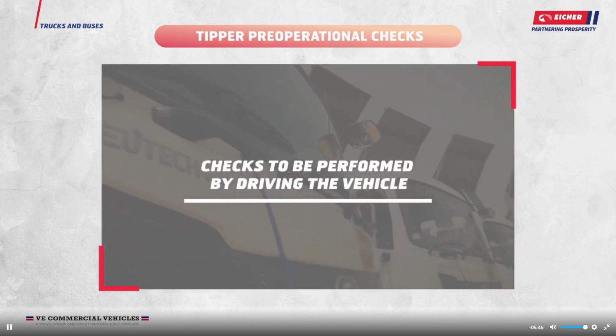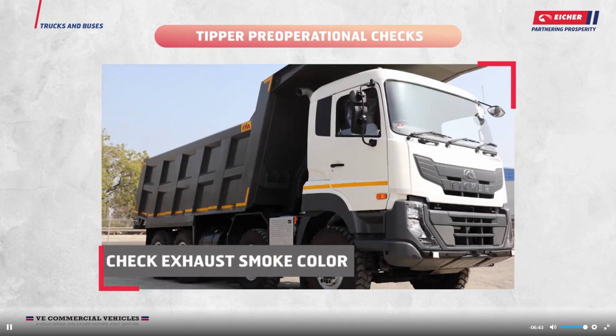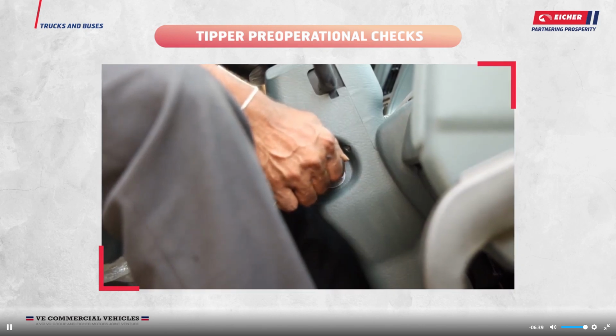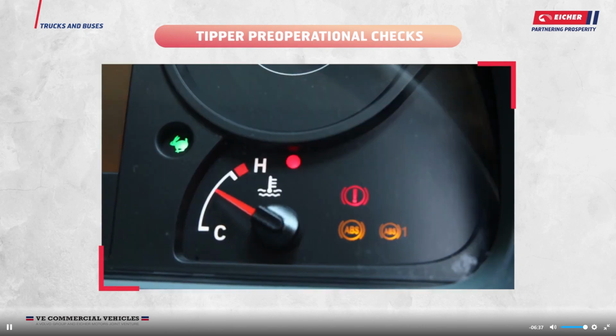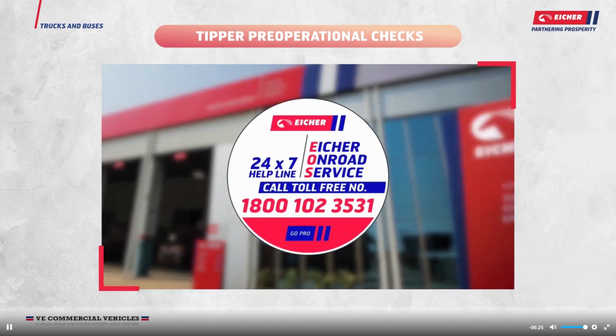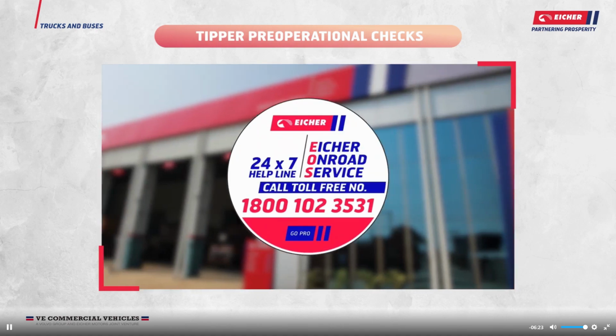Checks to be performed by driving the vehicle. Check for exhaust smoke color. Start the engine and let it run. Once it reaches to the optimum temperature, and then observe color of exhaust smoke. If smoke is colorless, then it is okay. If smoke is too black or white, contact nearest EICHER authorized service center.